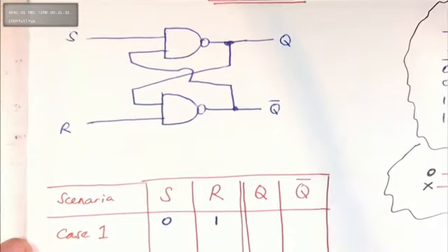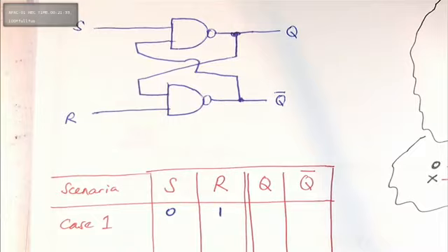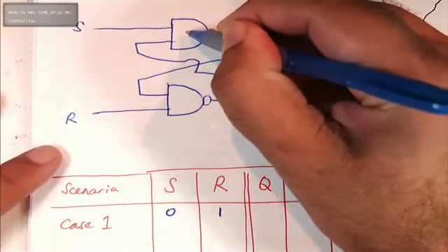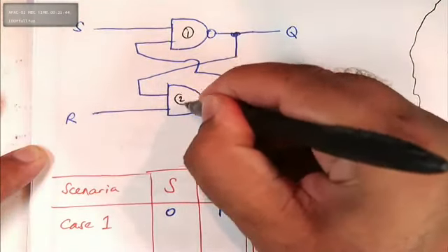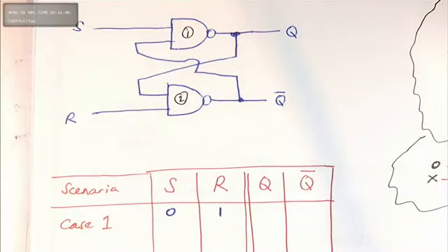All right, let's come here. Very important. Now let's look at the first flip-flop. I mean, the first NAND gate. That's NAND gate 1. Even though this numbering is not important, I'm just labeling it to teach you. In your normal circuit, you don't need to label them. All right, S is a 0. But you'll be scratching your head and saying, hey, what is the second input into NAND gate number 1? We don't know, because when we turned on the circuit, we don't know. How do we handle this situation?